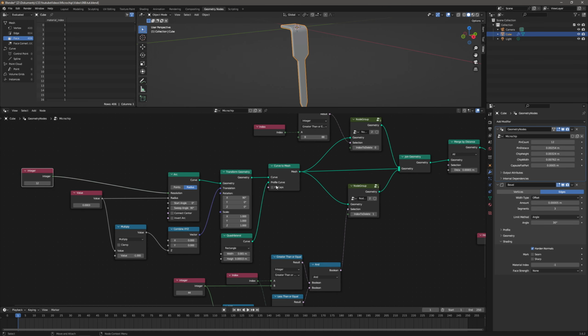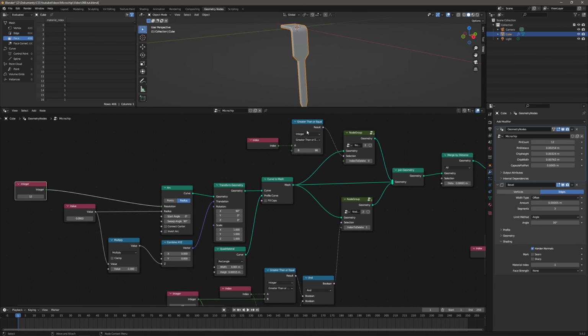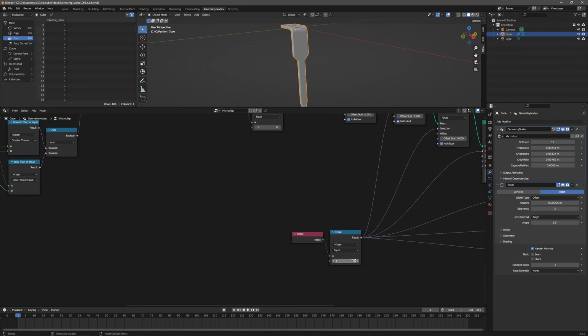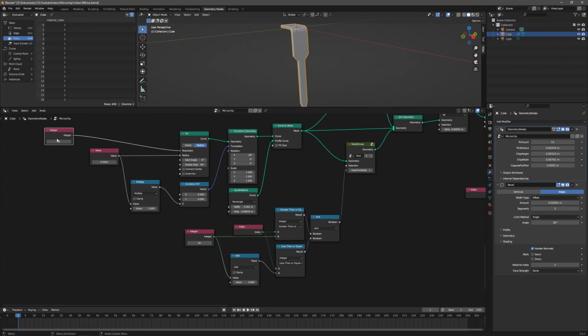I don't know if you noticed it, but actually this number is half of the top selection for the faces, and the index of the face that we are extruding is this value plus 1, and it actually works for all the resolutions from 4 to 36. What I tried. And the formula to calculate it is actually to multiply the resolution by 4.